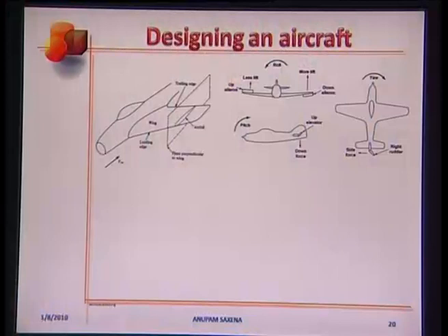An airplane is an engineering marvel of the previous century. The basic illustrations show different parts of an aircraft: the wings, the engine nacelles, which are not shown in the figure but which are below the wings, the fuselage, the airfoil, which is the cross-section profile of the wing when different cutting planes are used. The ailerons are moved up and down for the plane to roll.